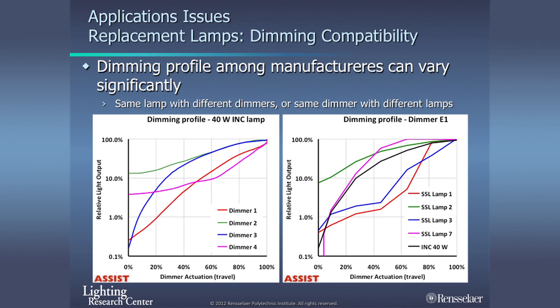And what you'd actually like to see is something like this blue line. You'd like to see that when you moved your dimmer, the light output went up in a nice arc, and that's what we expect. Now, what we're getting, though, are things like this, where nothing happens for a while, and then all of a sudden it pops on. They actually call it pop-on. And that's actually what happened there. What happened here is it went up to here and finally popped on.